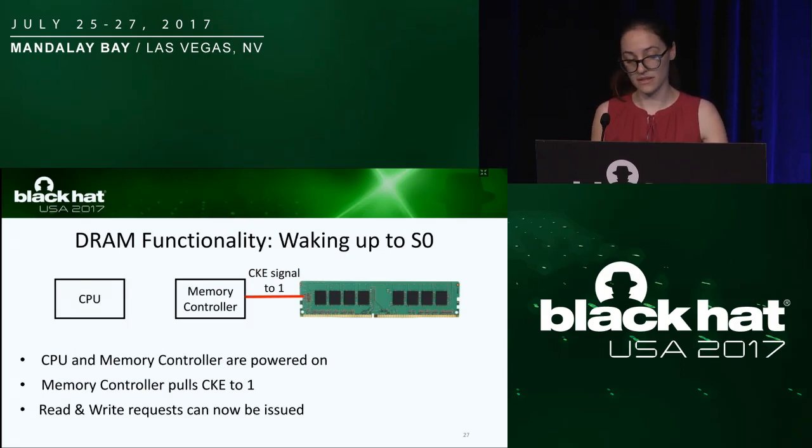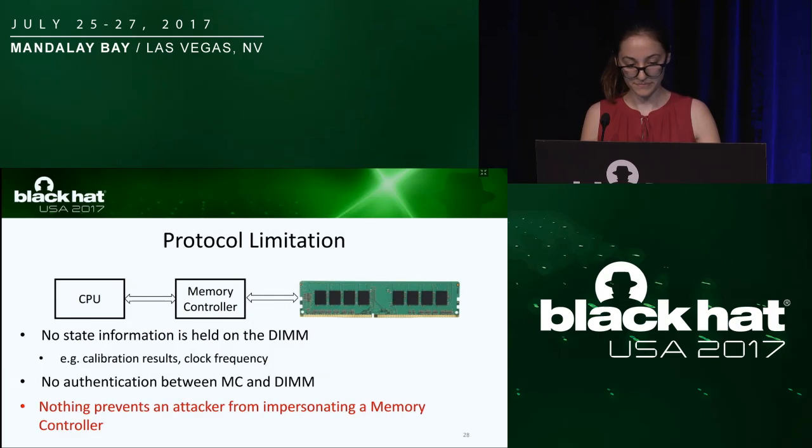And the moment that this clock-enabled signal goes to 1, then the DIMM wakes up, and then you can issue reads and writes again. And by waking up of the S0, again, the CPU and the memory controller is powered on, and now, and only now, you can do reads and writes again.